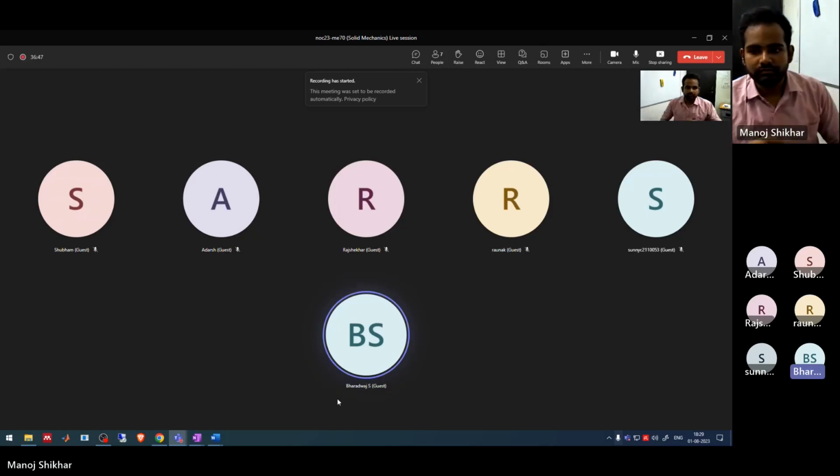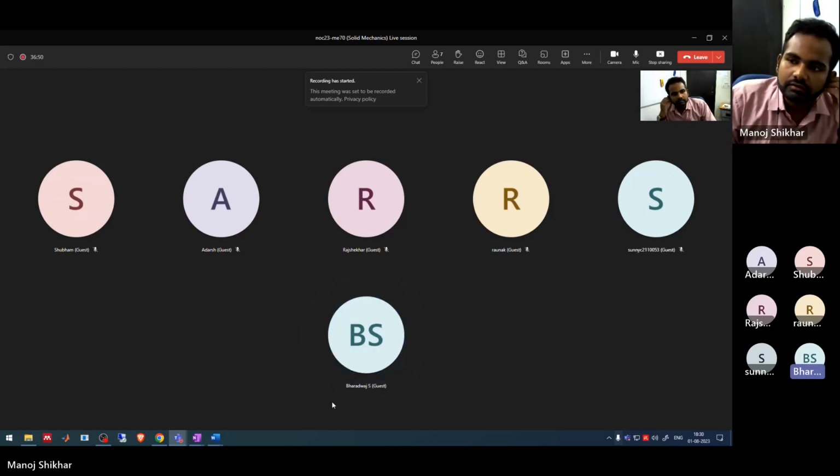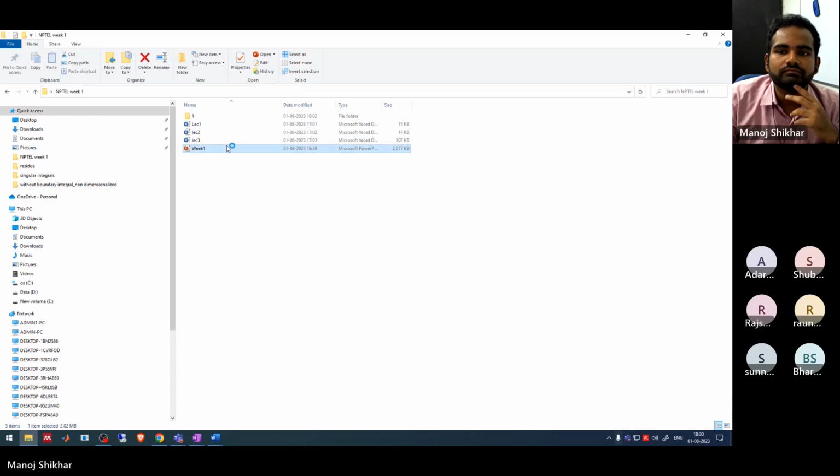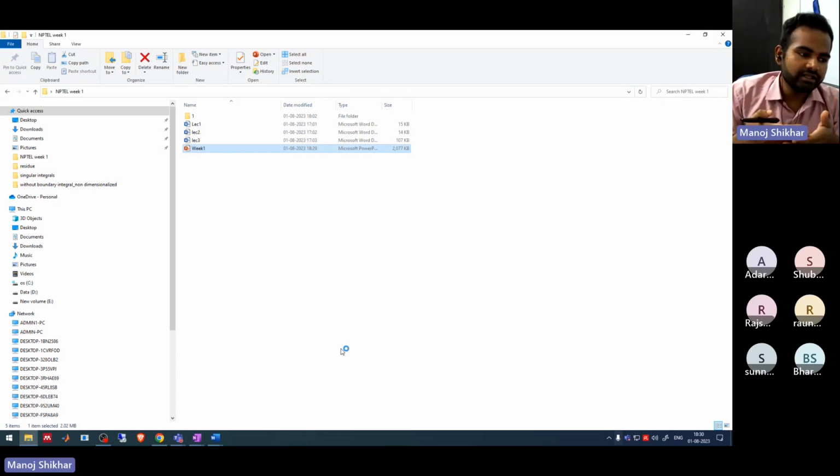The difference between traction and stress. So traction is the intensity with which, like the part we had separated, it will apply force on part A. So traction is a first order tensor. Okay. Stress is a second order tensor. Traction is basically a first order tensor. It will have a direction also. Stress is a matrix representation. And here, first of all, it is a second order tensor.